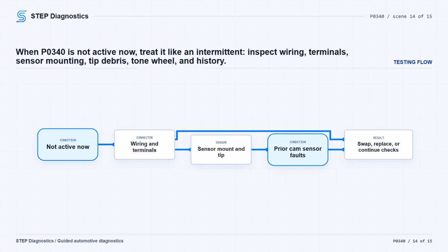If there is no repair history, exchange the cam sensor with the opposite bank and clear the codes. A poor connection at the cam sensor or PCM terminals, or a poor signal between the cam sensor and tone wheel may be enough to set this code, and unplugging and reconnecting connectors or repositioning the sensor may correct it. Confirm the code does not return, then complete repair verification.